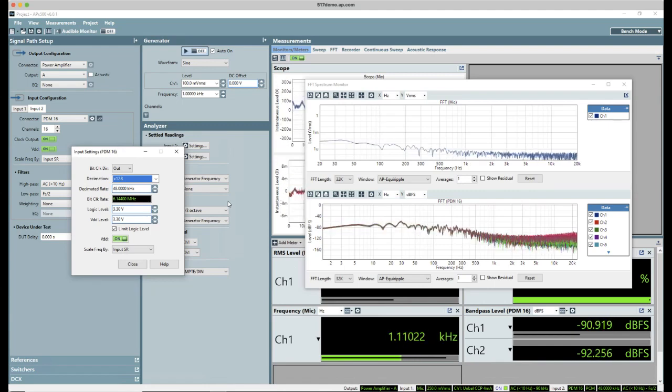So we just have to low pass filter and sample rate convert the signal. So we'll take a 3 megahertz signal, low pass filter it, that is, remove all the energy above our frequency range of interest, 20 kilohertz, and then we sample rate convert the 3 megahertz to, say, 48 kilohertz. That's how we get back to an audio signal.